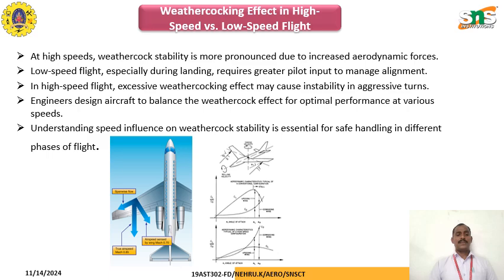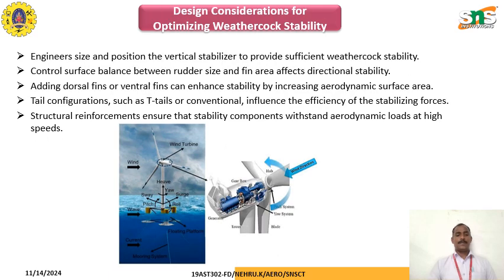Weathercocking effect in high speed and low speed flight. At high speed, weathercocking stability is more pronounced due to increased aerodynamic force. Low speed flight, especially during landing, requires greater pilot input to manage the alignment. Understanding speed influence on weathercocking stability is essential for safe handling in different phases of flight.